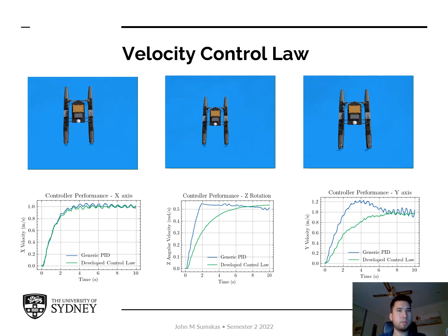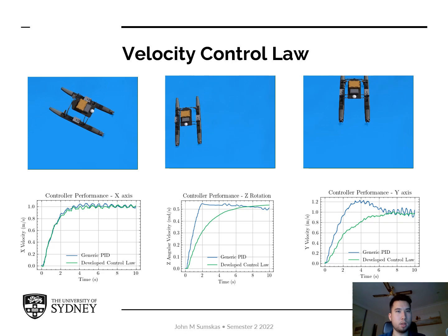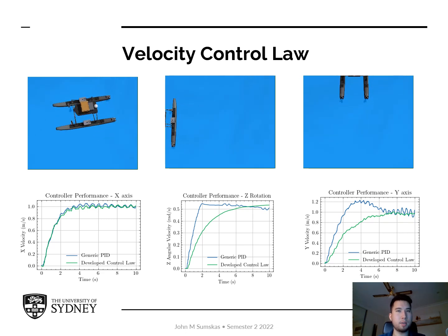The performance of the developed control law was assessed against a PID controller. The controller was tested in varying demands alongside different gains. Testing was also extended into varying disturbances such as winds and currents. Overall, the produced control solution was very stable and responsive under all scenarios, whereas the PID control solution would either very easily oscillate and be unstable in certain scenarios, or require a very low proportional gain.